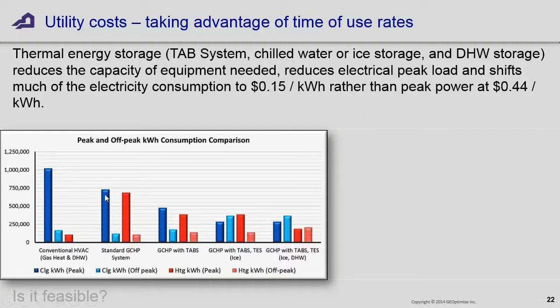A ground coupled heat pump system by itself will help reduce the peak cooling loads. Western Farmers Equipment Co-op has done some studies, drops it by about 0.6 kilowatts per ton. So that kind of thing is going to help. Just putting a conventional forced air geothermal system in there, water to air heat.